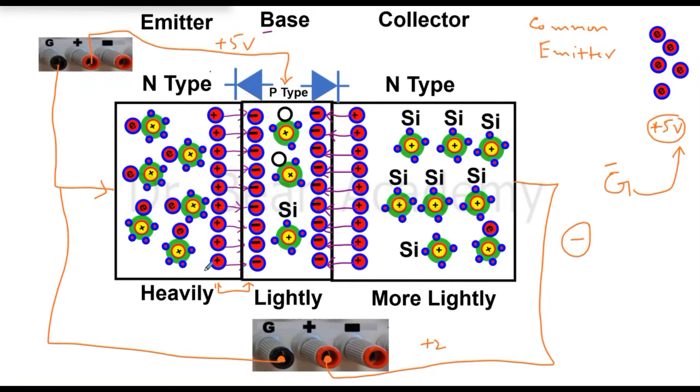If we can consider it as a p-n junction, then of course p-type side is connected with positive terminal of the battery and n-type side is connected with the negative terminal of the battery. This G, as I told you, is serving as negative terminal in this case, because the next point is at plus 5V. So in reference to plus 5, G is lower in potential in my convention, and it will serve as negative terminal. So this junction is now in forward bias mode.